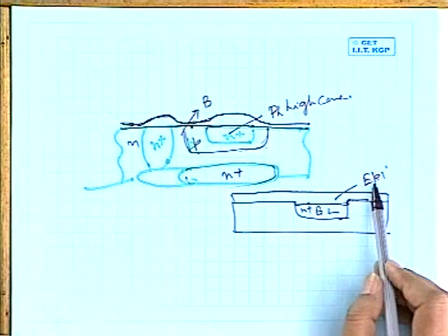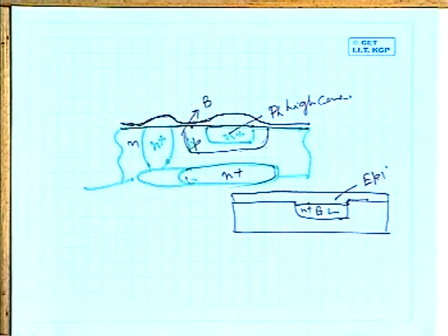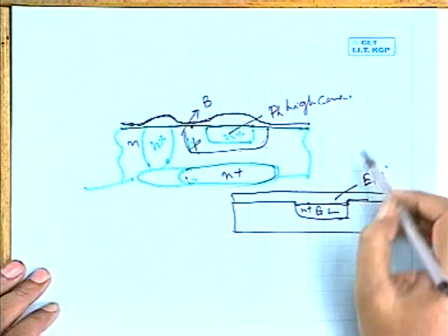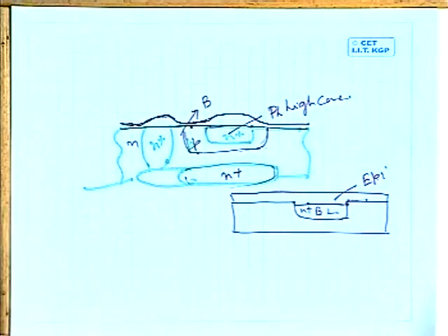So if the small groove is there and you grow the epitaxial layer over and above, that means in the buried layer region there will be a depression at the periphery. This is a cross sectional view, and if you see the planar view, there also you will see some depression, and that periphery mark of the buried layer will follow in the subsequent steps, and that will help you to align the further steps. So that is one advantage there.